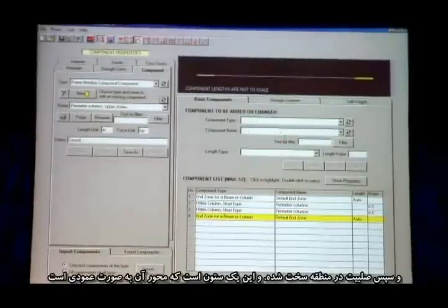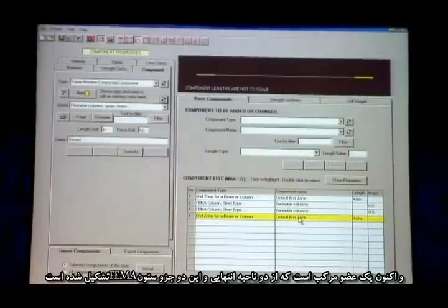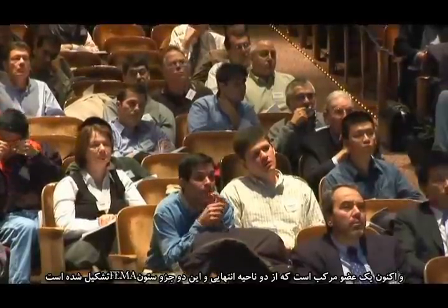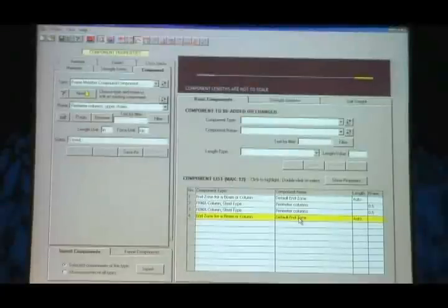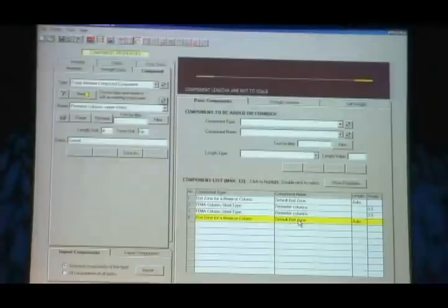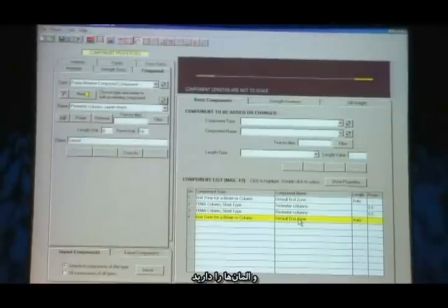This is a column, so it is actually vertical. So this is now a compound component, which is made up of 2 end zones and 2 of these FEMA column components. The FEMA column component depends on a cross-section. It's starting to get a little bit complicated. The next step, which I'll show later on, is you would then assign this component to an element. So you'd go cross-section, the column component, the compound component consisting of several of these things, and I'll do more of these examples later, and then the element.